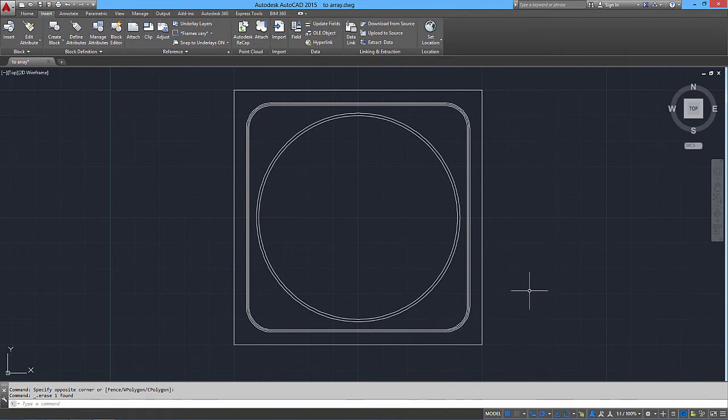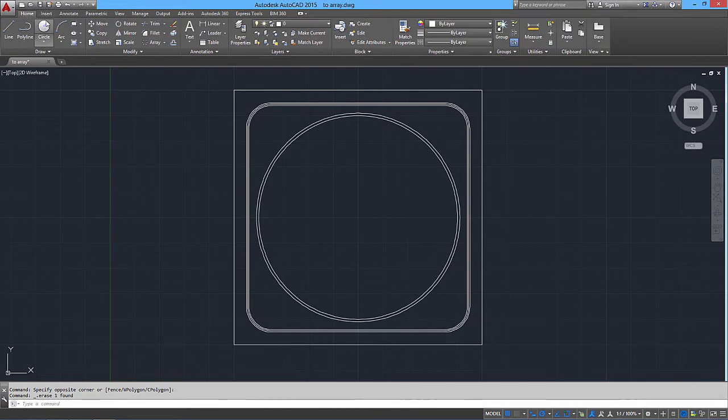Right, we are going to add 4 little circles into the center. These are on page 8, and then we're going to array the hour markers around the perimeter of the face, and they are all going to orientate themselves to the center automatically. So let's start by using the circle tool. That's on the home tab. So click on the circle.